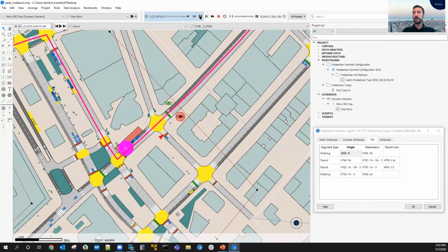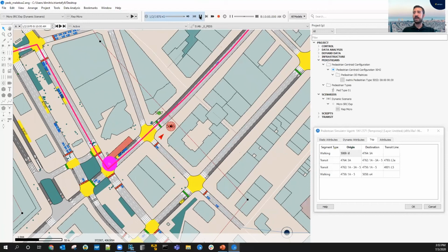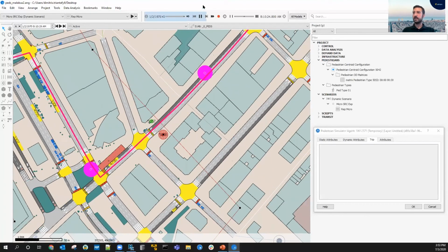That's amazing, because now we can model pedestrian agents as individuals. We can gather statistics. We can offer the user the modal split option. As we've seen in our example, when a bus arrives at a public transport stop, we can now see how many passengers are already on board and how many passengers board from this stop. So we have put together the mode choice for individuals to either walk and or use the public transportation system. How can we check results of this calculation? I will fast forward the simulation.